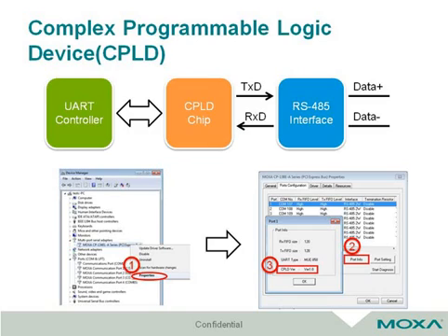For the CPLD version, you can find it in Device Manager. Expand the Multiport Serial Adapter tab. Right-click the product model, and then click Properties to open the configuration panel. Then, left-click Port Inform, and you will see the CPLD version. Because it's the first release, the version is 1.0.